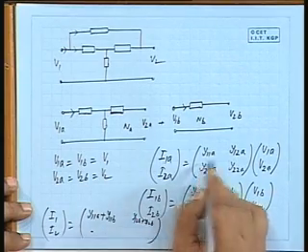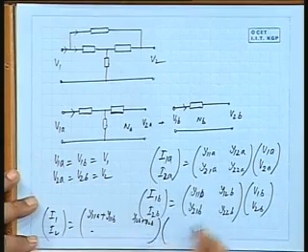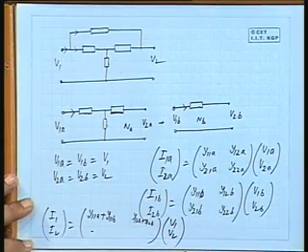That means element-wise you add the values of the Y parameters, and then this vector is the same as this, so I will write straight away V1 and V2. That means the admittance matrices are added together for the two sub-networks when they are in parallel. Is it all right?